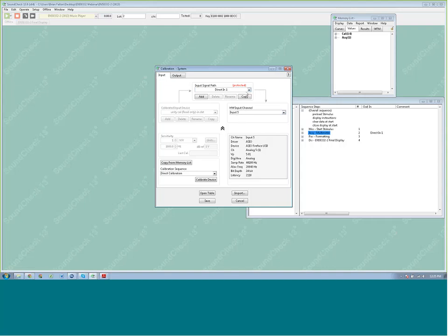The nice thing about using the direct in 1 is it's a protected signal path. We started including protected signal paths in, I believe, SoundCheck 12, or maybe it was even 11.1. And protected means that it's locked down. You can't change the sensitivity or the device, which is ideal in this case, because we want to use unity cal, 1 volt per volt for the sensitivity, because what we want to monitor here is what voltage is being produced by the device under test. So by leaving this all set to unity, we'll be looking at just the voltage coming into the system.